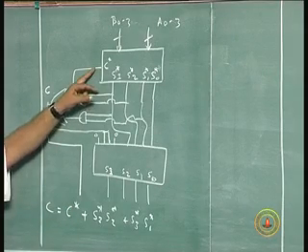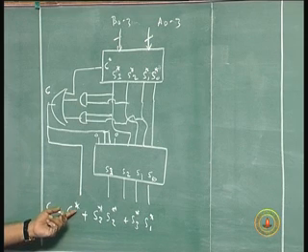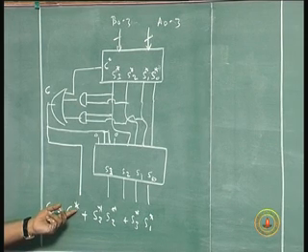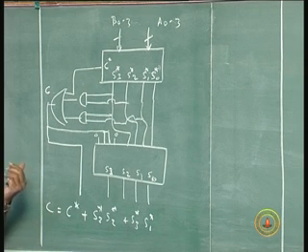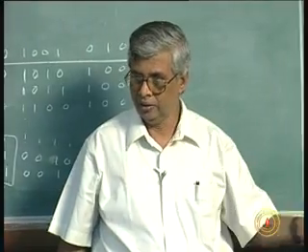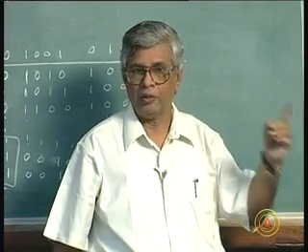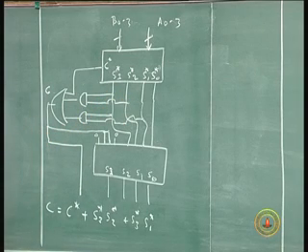If the original addition results in a carry, for a number greater than 15, this C star takes care of 16, 17, 18, 19, because 4 bits can only represent 0 to 15, but the number can be anywhere from 0 to 19 theoretically, practically 0 to 18.